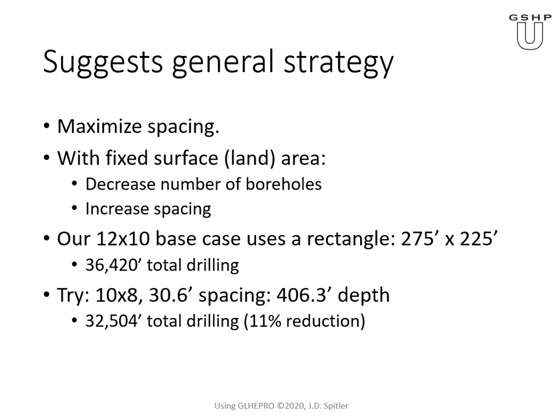So I looked, we have a 12 by 10 base case, right? That means there's 11 25-foot spaces in one direction and 9 in the other, so that's 275 feet by 225 feet. And we had then 36,420 feet total drilling. It may not have been quite that. I just multiplied the 303.5 by 120 boreholes.